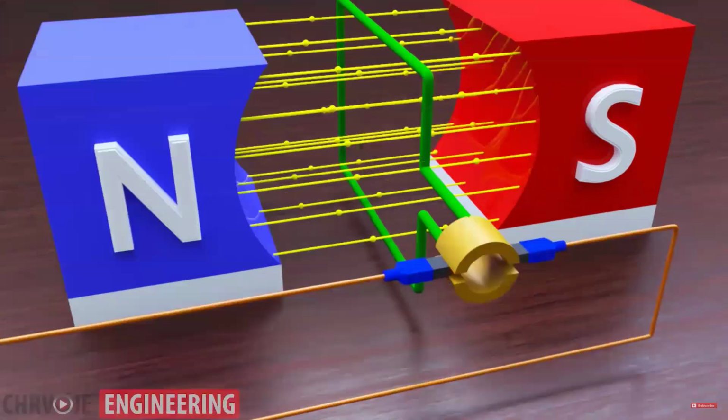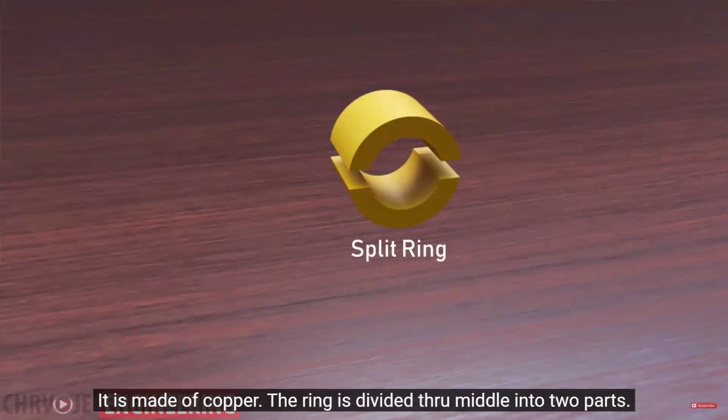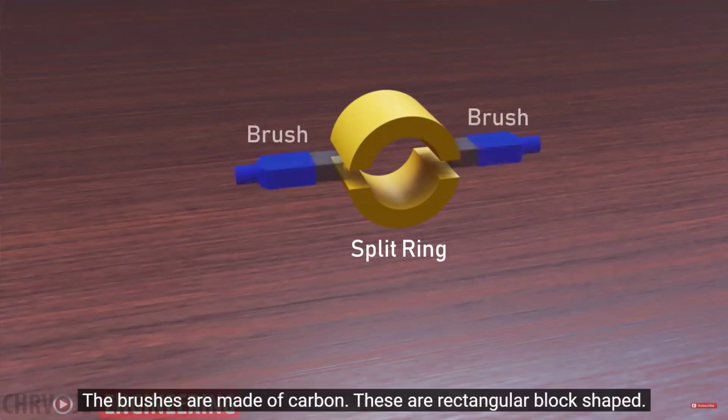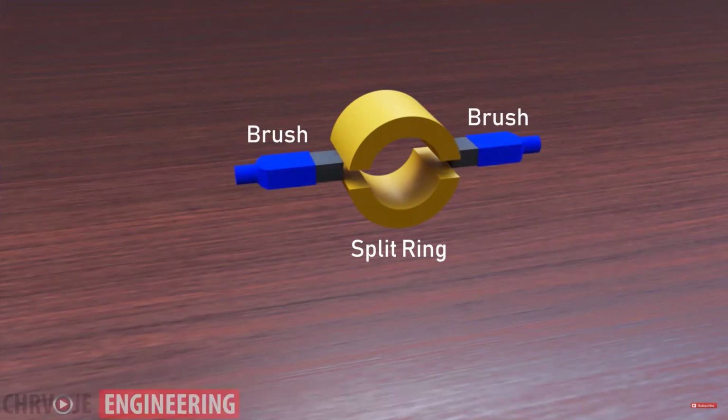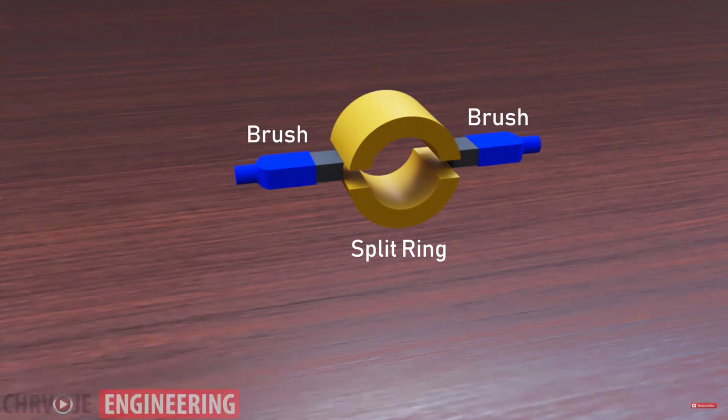The armature loop cuts the magnetic field, due to which an electromotive force, EMF, is induced in it. The split ring is a movable device used for reversing the polarity of the current. It's made of copper. The ring is divided through the middle into two parts. We must use the split ring to achieve a single direction of current. The brushes are made of carbon. These are rectangular block-shaped. The only function of these carbon brushes of a DC generator is to collect current from commutator segments.